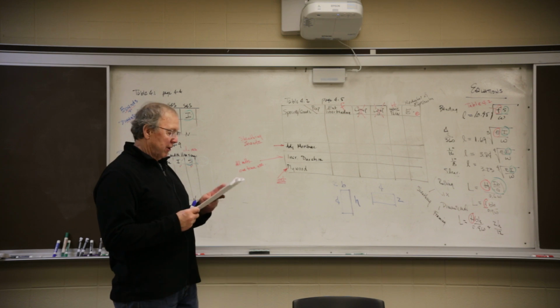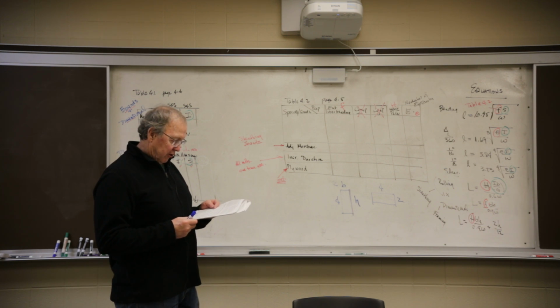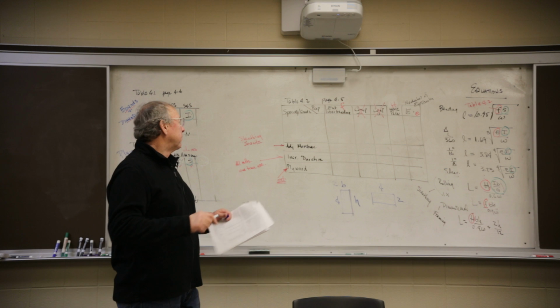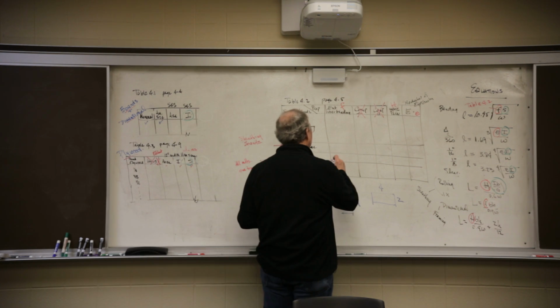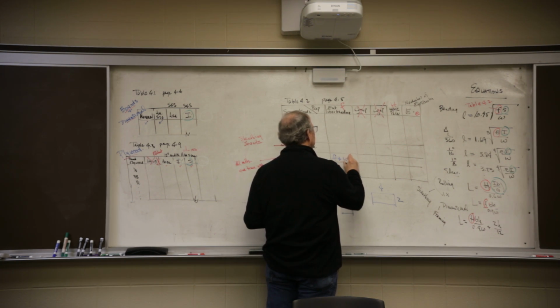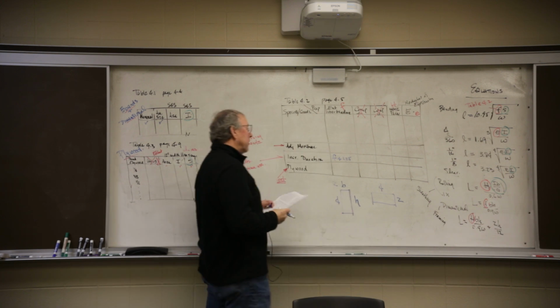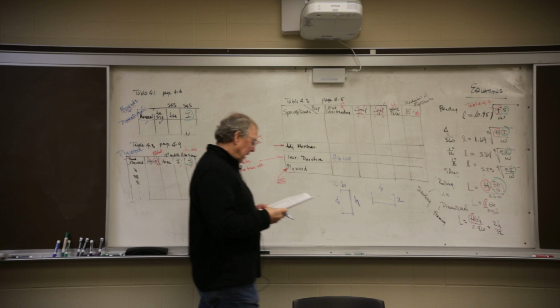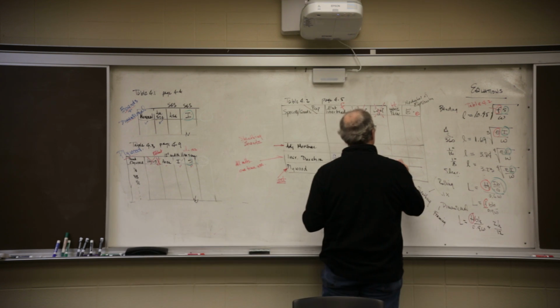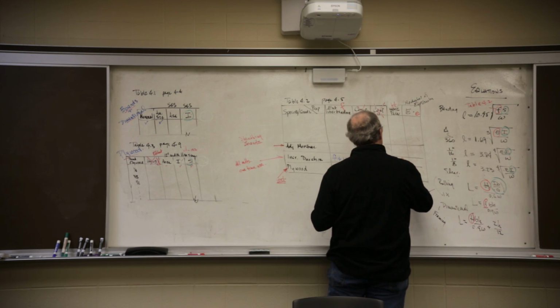I'm going to change the numbers here. You can see it says for bending, add 25%. So we're going to multiply FB here, little f, times 1.25. Okay. Move on. It says horizontal increased by 1.25. So we're going to take H and multiply it by 1.25.